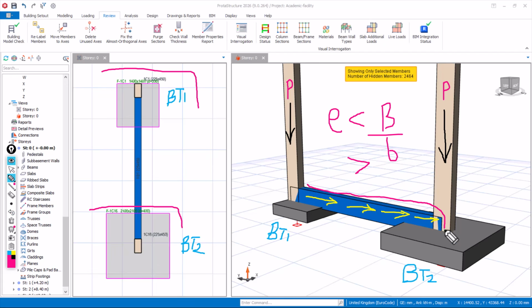So this is a strap beam which takes care of what? The overturning. One, it also stabilizes the soil under this footing, causing a uniform footing. Then it also transfers the load from this column through this strap beam, which you're seeing with this arrow here, onto this interior footing. So this is the concept of a strap beam.